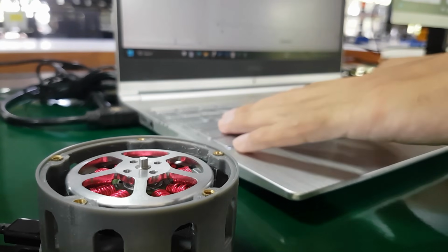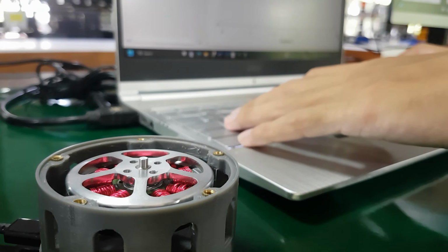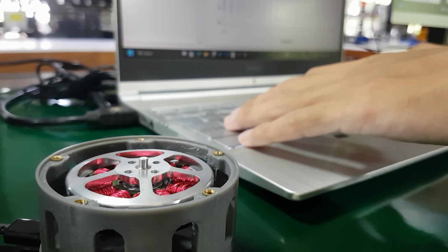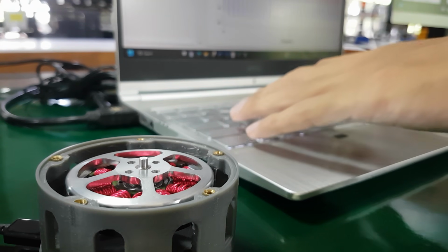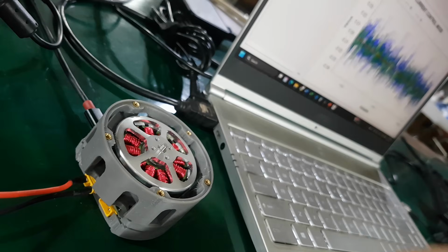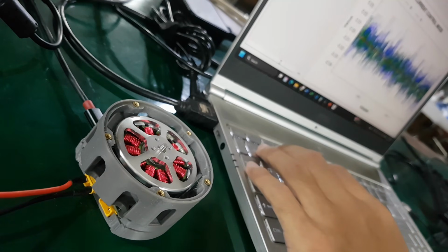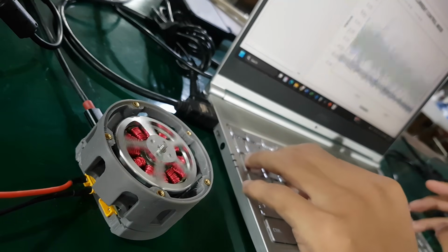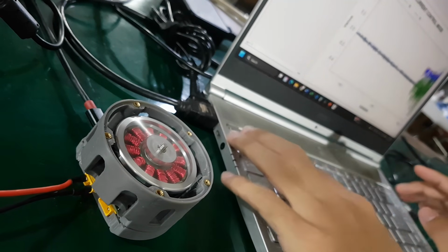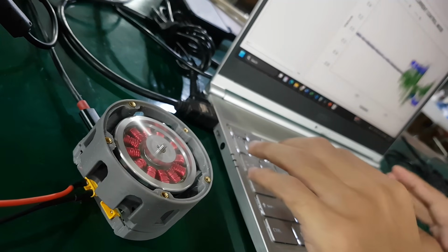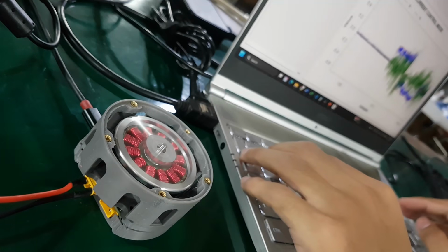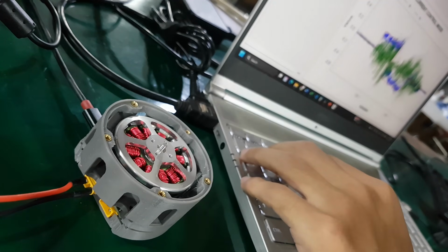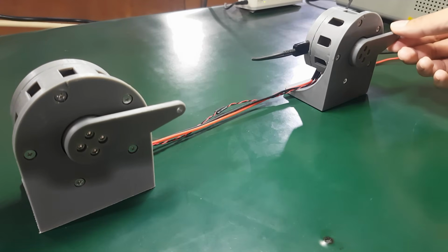A small step toward a truly autonomous FOC system, one that can recognize its own motor characteristics without the need for external measurement equipment. Even more exciting, this method can be further developed to estimate other parameters such as back EMF, flux linkage, rotor inertia, and more. Imagine, with a smart motor driver, we're not just controlling the motor, but also understanding it on a deeper level.